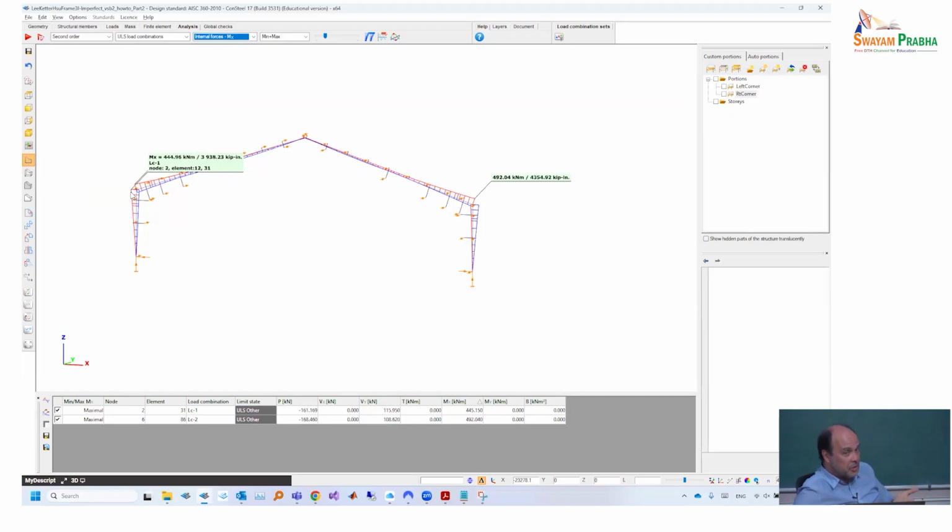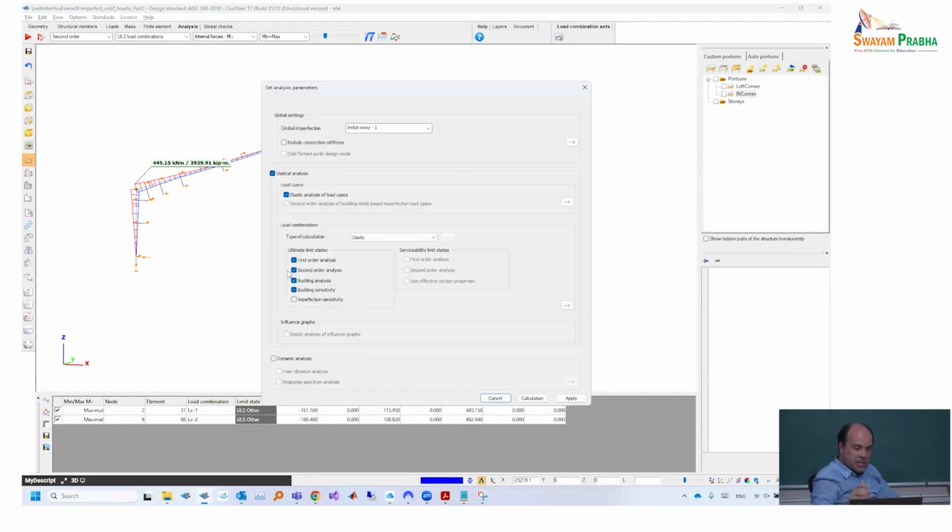So based on this calculation, those 16 modes which were calculated, which are fulfilling this requirement that have a load multiplier less than 20, none of them was found, assuming that the wind is always blowing from left to right. Of course, if I was adding the other type of wind direction, then I would see the load combinations which correspond to those which produce the relevant effects on the right side column. The mirrored load cases would give now the same results to this column. Okay, so this is buckling sensitivity.